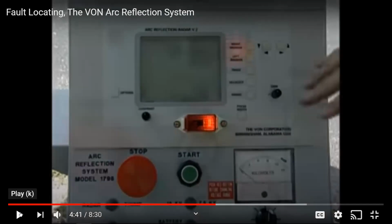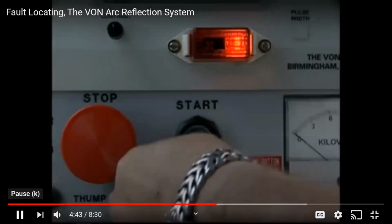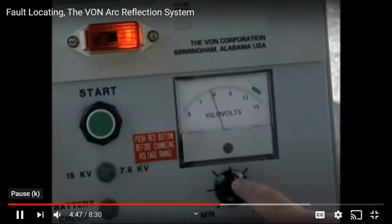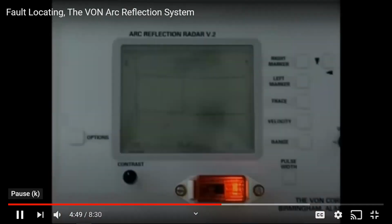Okay, so you're actually in radar mode right off the start. Now, how much voltage am I putting on the cable? None. Zero, none. You're in radar mode right now, okay? And we'll talk about something here in just a moment. Next, push the green start button. The unit will charge to the level you've set on the indicator. It will then discharge, and the fault will automatically be marked.